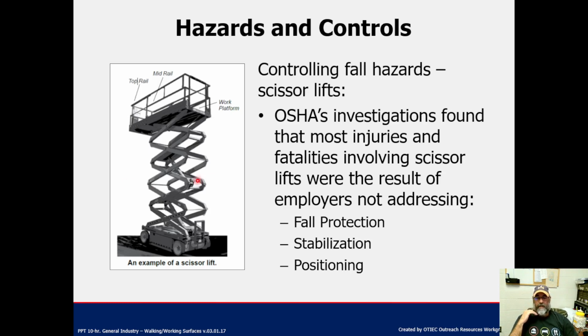Scissor lifts. I wouldn't go on a scissor lift. Most injuries occur because you're not having fall protection, you don't have the proper stabilization, or it's positioned incorrectly. These things need to be perfectly level when you're setting them up. If they're not stable, if they're on unstable ground, if you don't have fall protection, you lean up against the railing and down you go.